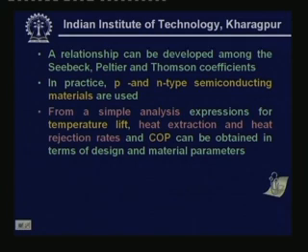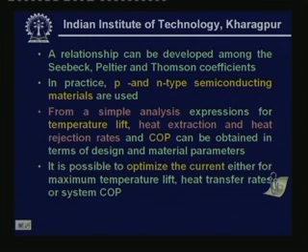From a simple analysis, we can derive expressions for temperature lift, heat extraction and heat rejection rates and COP, in terms of the design and material parameters. And it is also possible to optimize the current either for maximum temperature lift or for maximum heat transfer rates or for maximum system COP.